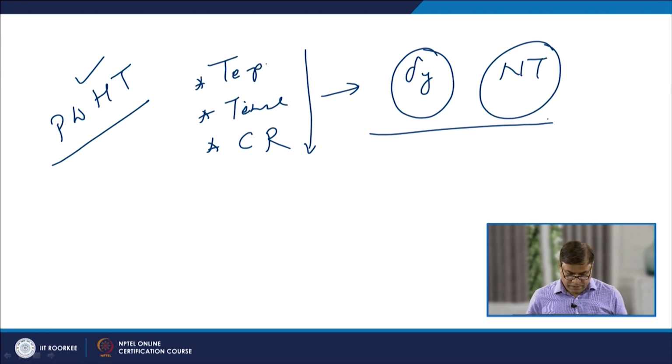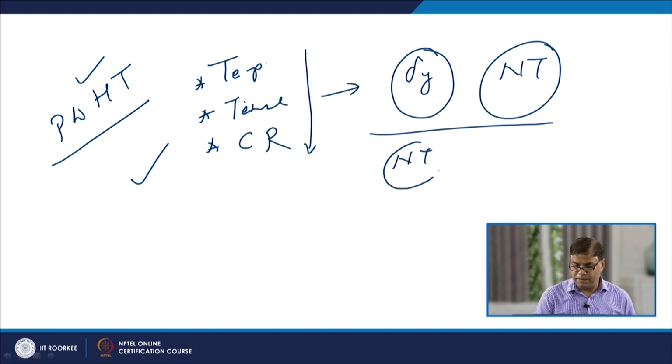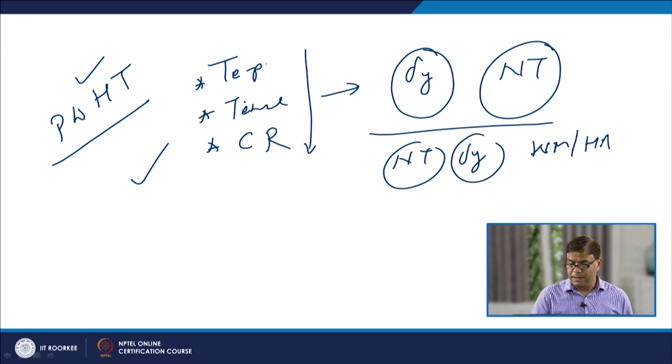coupons of that metal system, so that after establishing the proper post weld heat treatment conditions, the heat treatment can be given to the actual or the real weld joints, and these things are especially needed to restore the notch toughness and yield strength of the weld metal as well as HAZ if these have been compromised during the welding of the steel.